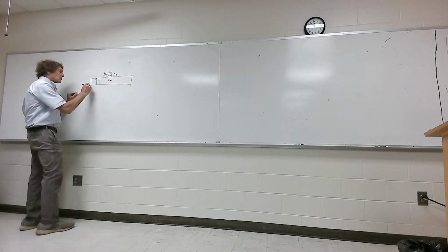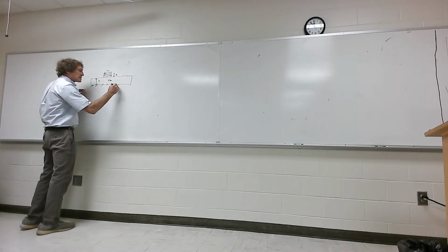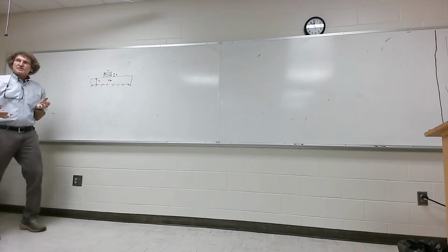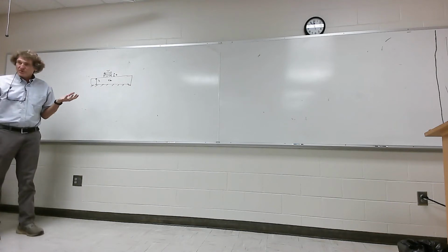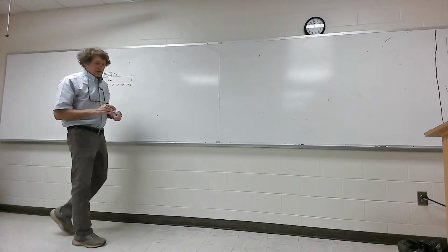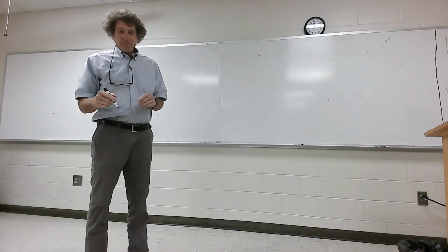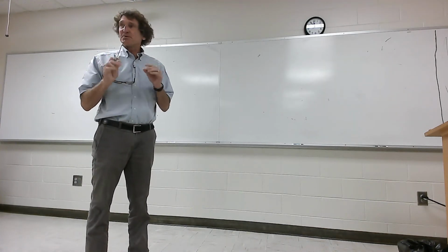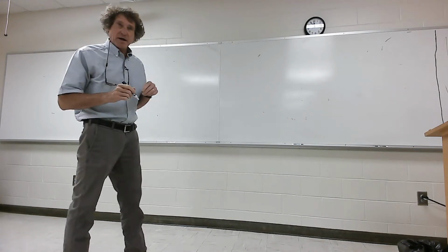Now, the back of this board is also grounded, so this is like copper clad. And I told you last time, you basically get rid of the copper you don't want and use that as a strip line that will have a characteristic impedance. Do y'all follow me in that? Just like a waveguide. Now, but these things are not waveguides, they're transmission lines. So think transmission line, not waveguide.